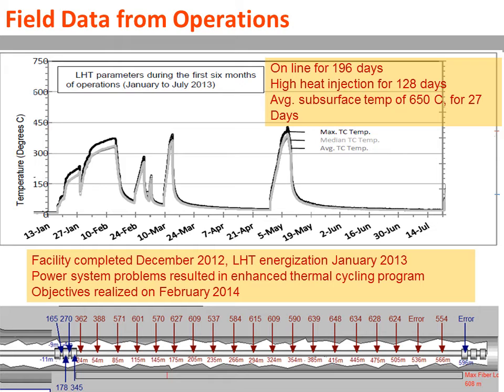If you have the same thermal diffusivities in the near wellbore, you're going to get fairly good temperature consistency along the horizontal well. One of the things we were interested in here was drying out the well. We had two different regimes basically, where you initially have moisture water in the near wellbore, then you drive that out, and then you have conductive heating into the formation. And we had both of those basically going on in our testing.